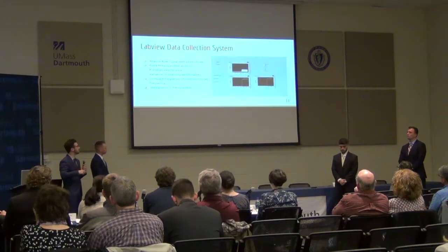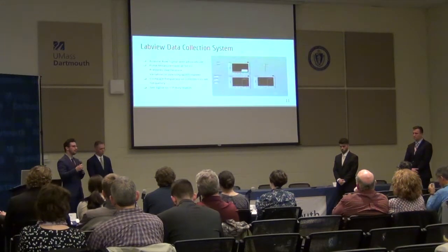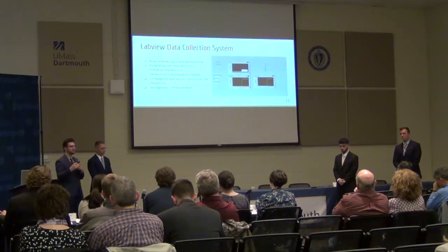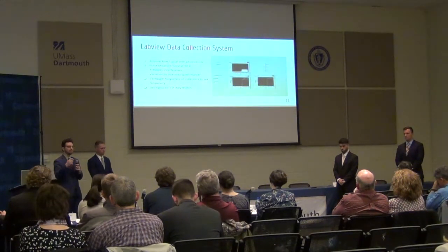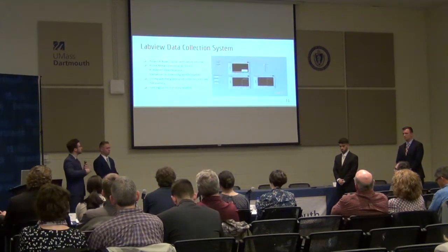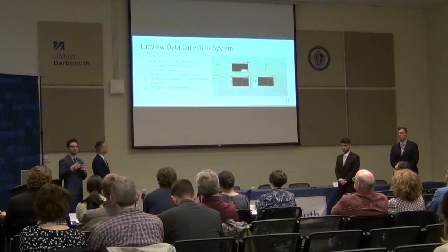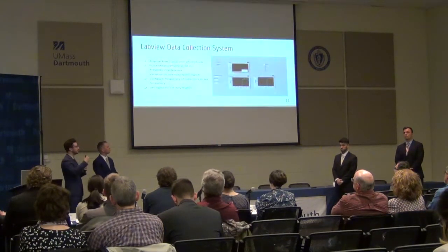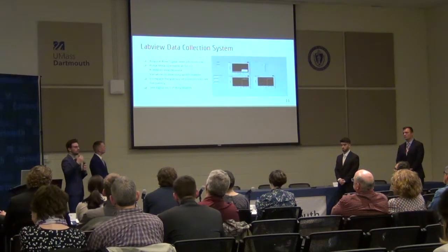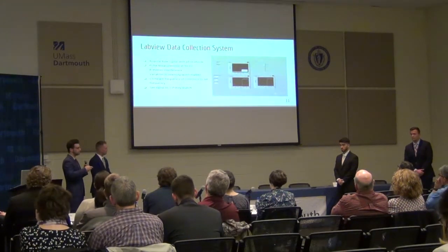Just below that is a frequency reading. What we have our detection set to is to respond to a frequency of 50 Hertz plus or minus 10%, and that value, when it's reached, gives us a step function from 0 to 1. That's what we're looking for from a detection, because it's the light coming from the LED, and in every activation, that's the main focus for it.